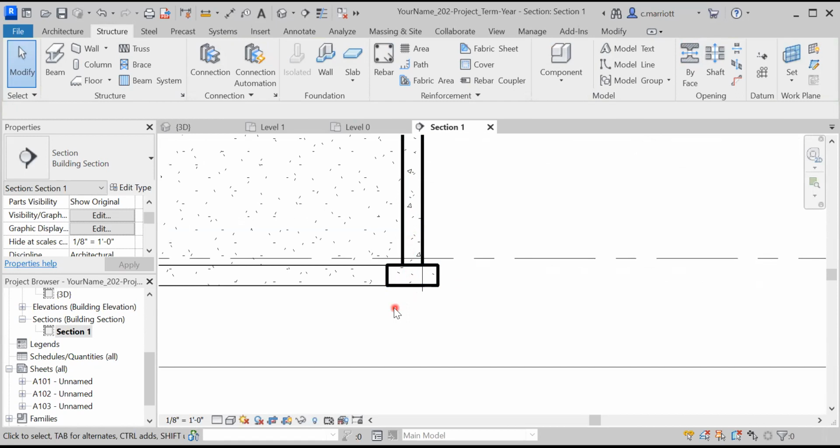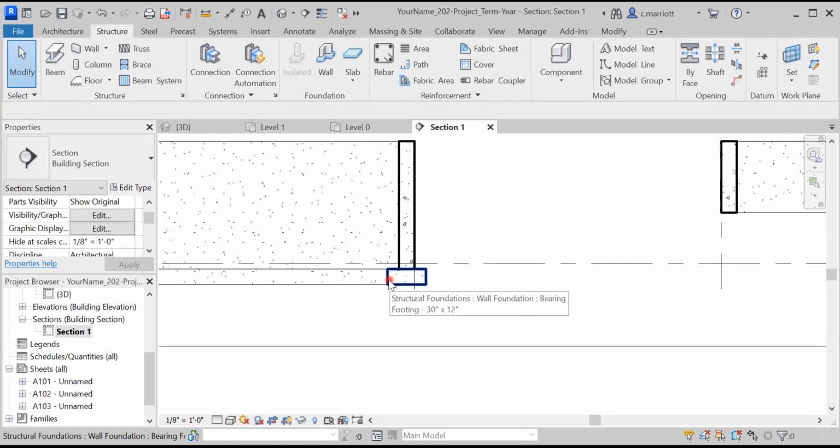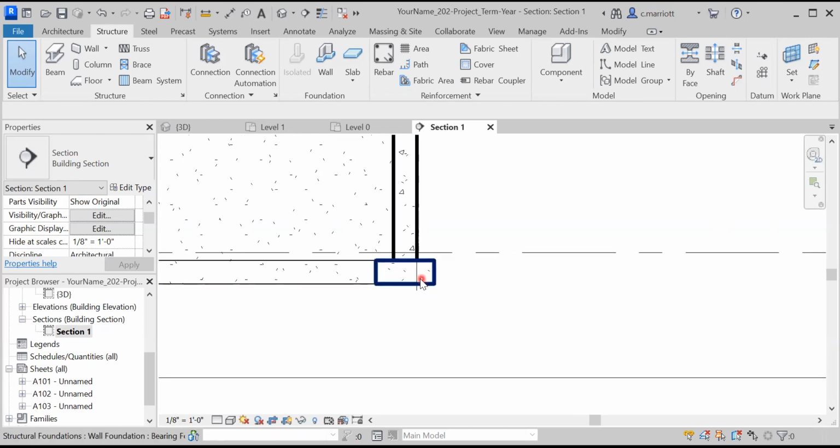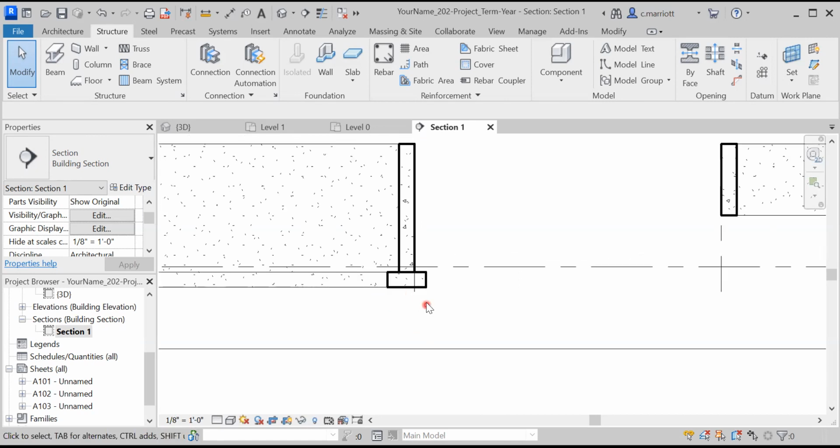So it really comes down to the soil conditions. If the soil conditions are not good, you may need to create a wider footing to better distribute those loads. If you have really good soil, good drainage, the right kind of combination of soil components, whether it be sand or rock or some combination, that would kind of impact this. You could probably go with a smaller one.